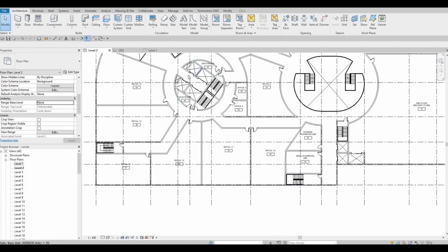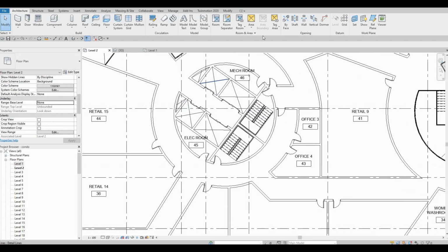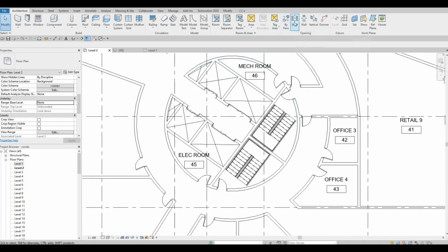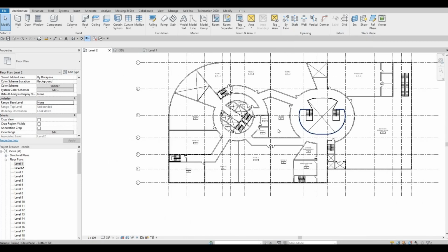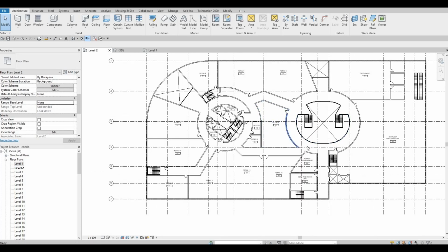But here it's gonna be different. It's better to use a shaft instead of opening each and every floor. You can do that when we group a floor. So you could just click on open or create an opening from each floor because everything is grouped. But at least this is the proper way of doing it if you want to do. So I'm gonna show it to you guys.